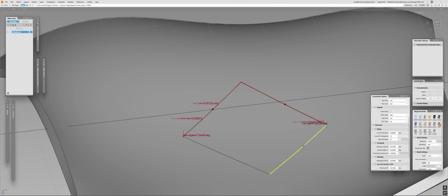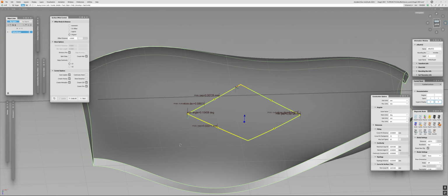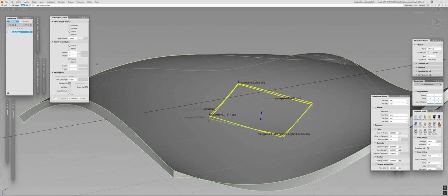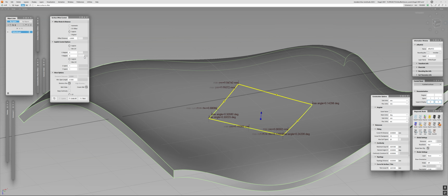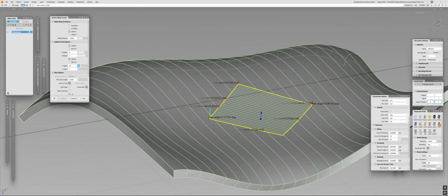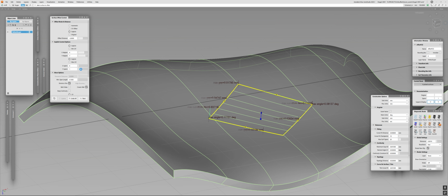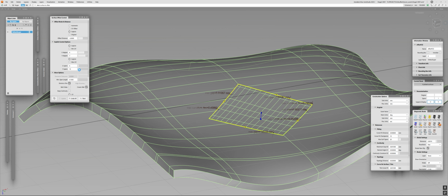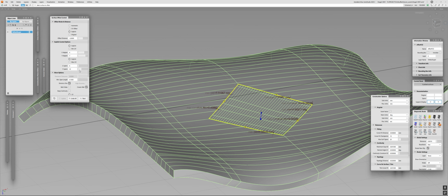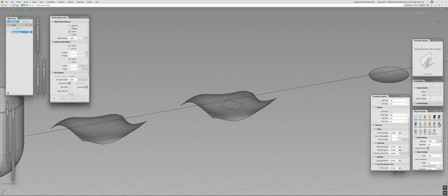But if you check it, you're going to see that it's kind of accurate, but not accurate enough, right? Well, okay, let's go to the explicit then, and we just try to increase the amount of degrees ourselves, right? And you increase and increase and increase, and it becomes difficult. Now, what was that? Well, that's because these different surfaces have a very different parameterization. They are not following the same direction, not even close. They have a different amount of degrees between each other, and they are not periodic. So in this regard, the better solution will be to use automatic instead.